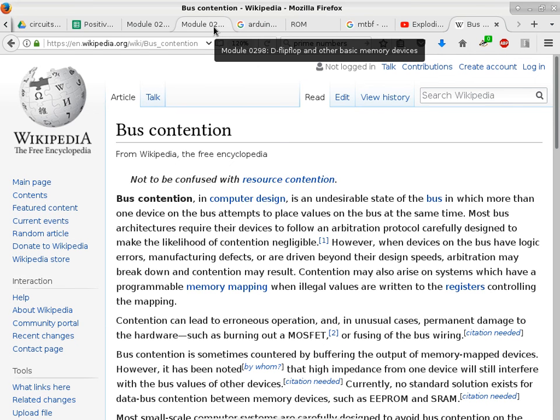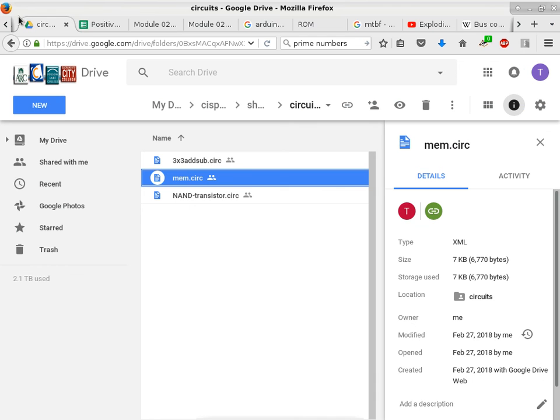So are there any questions about everything that we talked about today? No questions? Okay. So on your own, before Wednesday, I want you guys to read ahead of me, so you read about RAM. So the only difference between RAM and ROM, which is kind of minor, but it's also major, is RAM is random access, it is read-writable. So that is interesting because we need an extra pin to specify, are we going to write to RAM or are we reading from RAM? That is just kind of natural. You need one more wire to control what is the function of the chip.